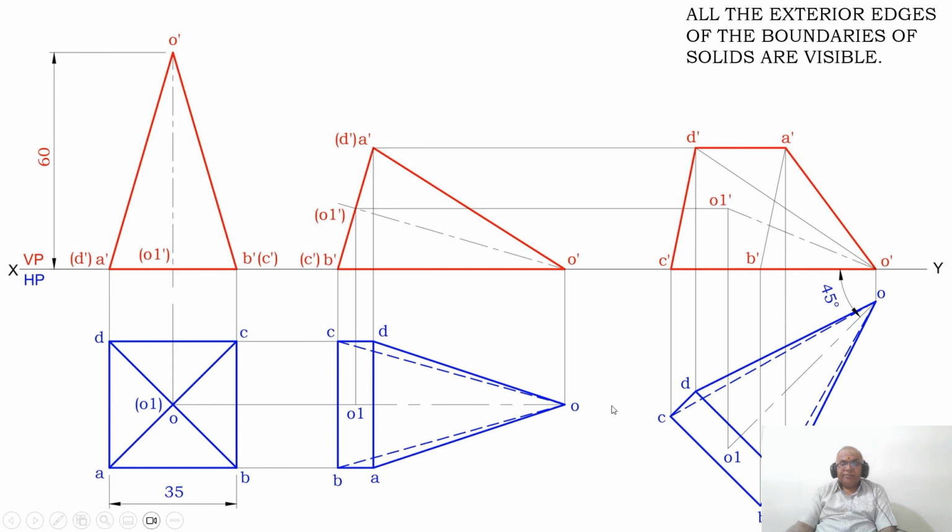Then rewrite the same sketch, including the visible edges and invisible edges of the second position top view, onto the third position top view without changing anything. Then I need to draw the front view.